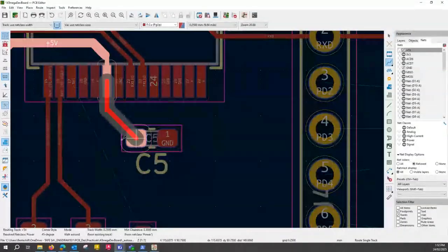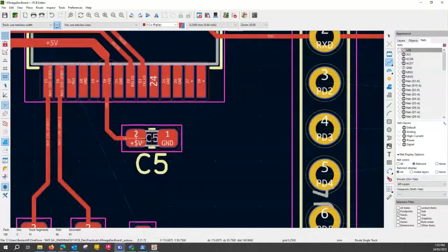We want connection there. You don't want diagonal connections. It's bad practice. The system should understand that, but it doesn't. So what I'll do is I'll connect through the end. Now, why do we actually route to the back of the component all the time, not to the side of it or on an angle? The reason for that is that the copper might pull, depends on your clearances and gaps.